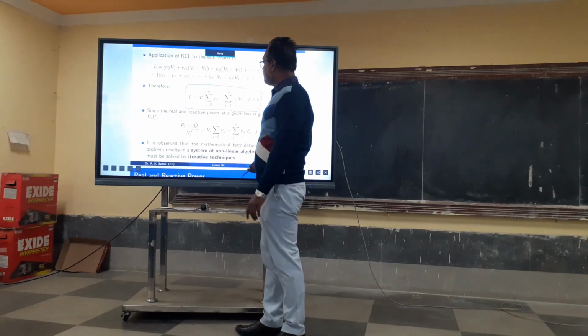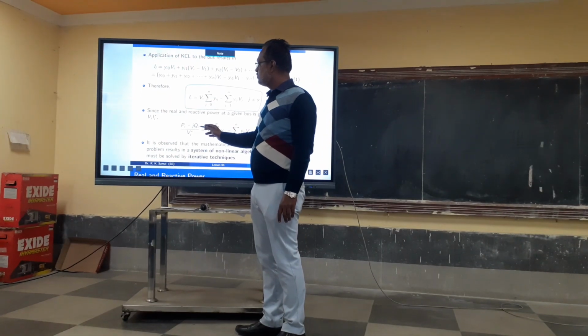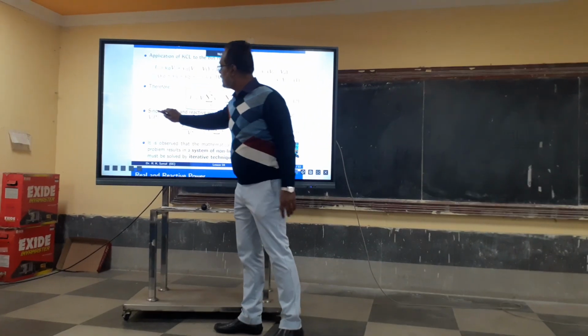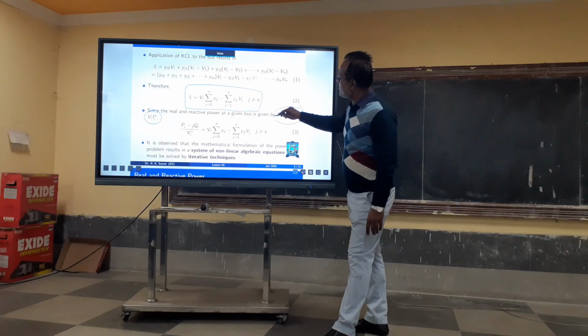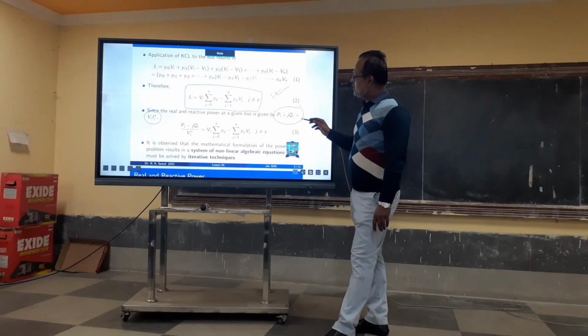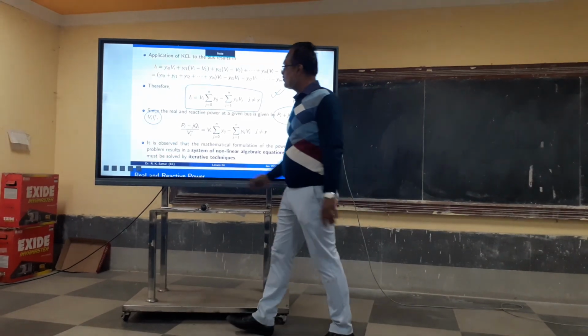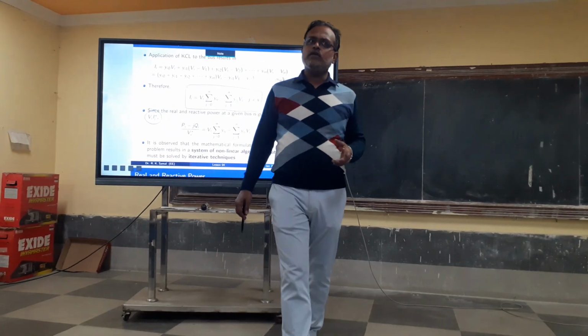The objective is to compute the total power flow, which is Pi minus jQi equals Vi into Ii conjugate. So write down these equations here, right? First is computing the current from the voltage and admittance. Then computing the power using the complex power formula that we discussed in the very first class, Vi Ii conjugate. Okay. And why do we use this conjugate?